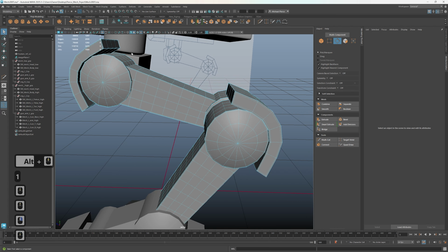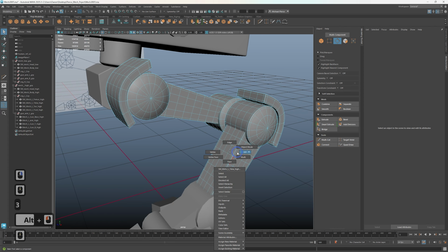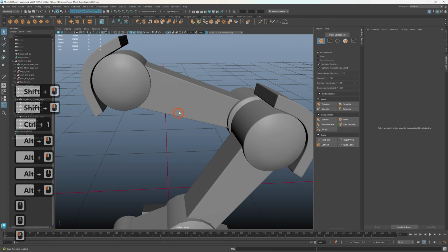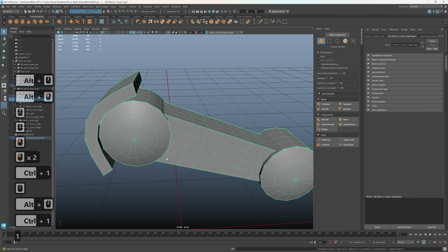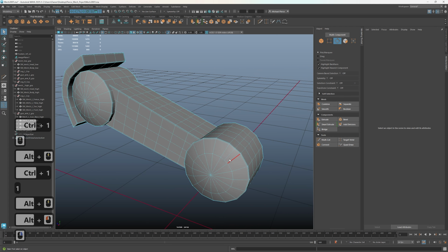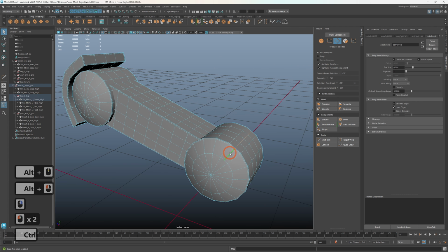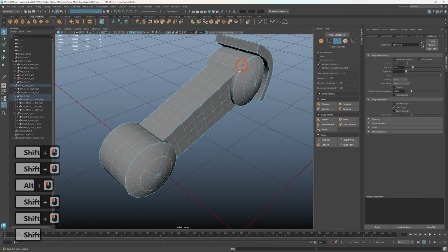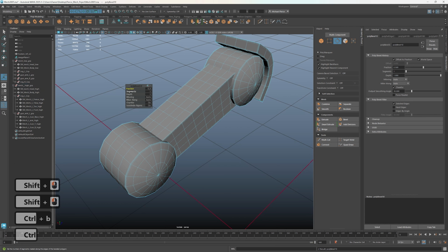So if one were to come back right before you do anything, right? In fact, I'm going to grab 1, 2, 3, Control 1. Actually, I'll do one at a time. Let's see here. I'm going to hit this. Oh, I'm going to make sure I take out this accidental edge that I added in. That way it'll smooth nicely. I'm going to grab these edges right here, because I'm also going to copy the effects. So let's just go B. I'm going to leave with the chamfer, but I am going to do like 0.25, right?